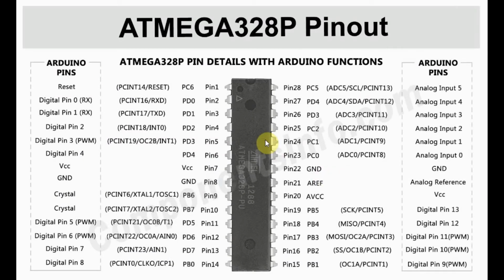The heart of the Arduino Nano board is the microcontroller Atmega 328P, which has 3 I/O ports: port B, C, and D. For the 3 I/O pins we want to reprogram as PCI pins, we need to locate their position within the ports. So for example, digital pin 4 is at port D, digital pin 13 is at port B, and analog input 5 is at port C.